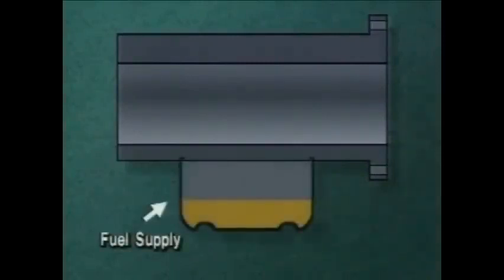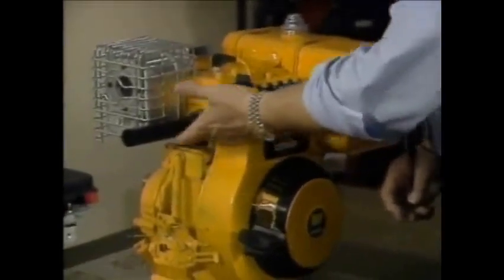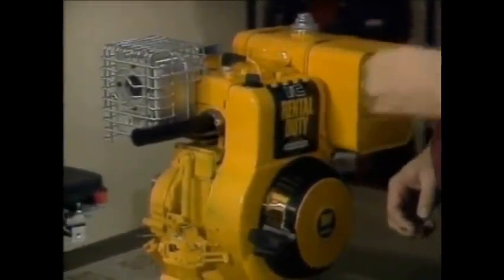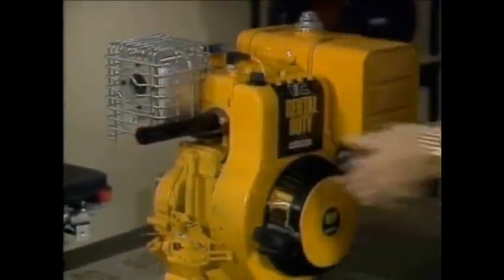First, we need a fuel supply. We take care of that by adding a bowl of fuel below the tube. But that creates another problem. How do we get the gasoline from the bowl below the tube into the air passing through the tube? Now here, we have to refer to Bernoulli's principle of fluid flow. We can treat air as if it were a fluid and apply part of Bernoulli's principle to our carburetor in order to get the fuel out of the bowl and into the airstream.